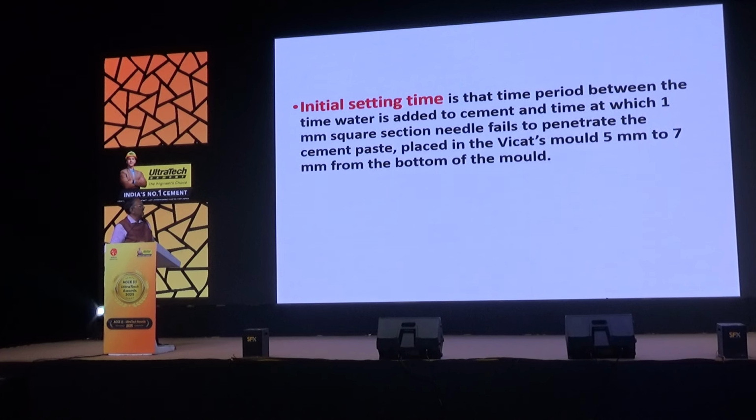Next is the setting time, initial setting time. We all know the normal initial setting time is 30 minutes, but we can delay it by using retarders. So we have to design the retarder, and I have many stories on retarders also. Long back, about 25 years back, when ready-mix concrete was new, we had a concrete slab never setting even after 48 hours. Initial setting didn't happen.